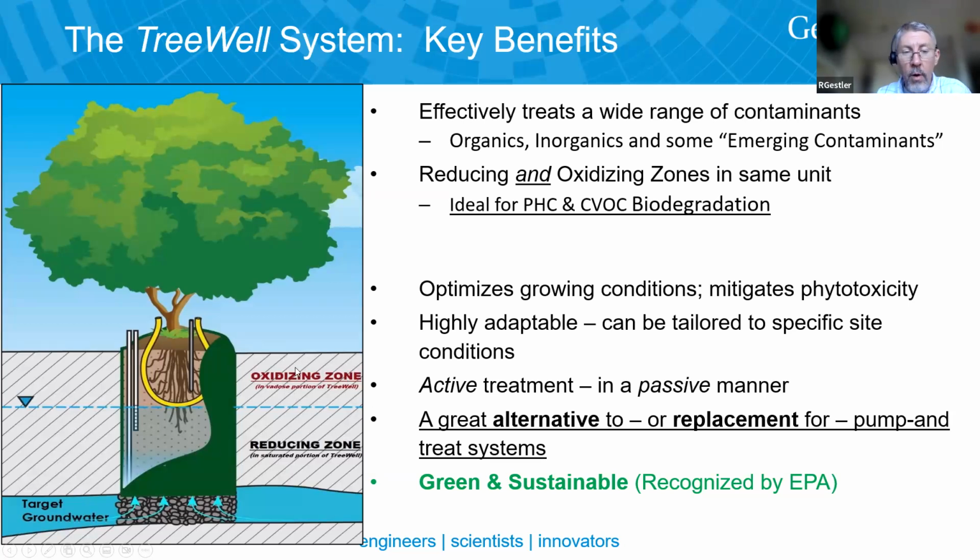So where the roots are within the vadose, a very oxidizing zone. Remember, we've got that passive aeration tubing there to get oxygen into the root zone and other undesirable gases or volatiles out. Conversely, below the water line, before the elevation of water, we have strongly reducing conditions. We're actually putting quite a bit of organic material in there to drive to reducing conditions.